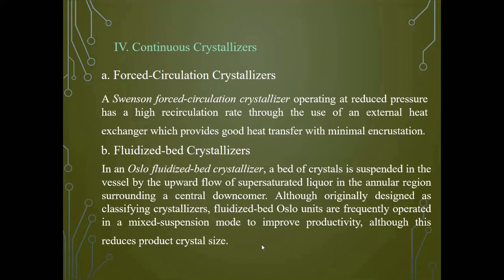So there is an opening in the crystallizer unit, and your supersaturated liquor remains suspended in the annular region surrounding this central downcomer. Your unit is in a mixed suspension type of mode, meaning a certain amount of the grown crystals remain suspended in the solution while new ones are being processed. That is why it's called mixed suspension mode.